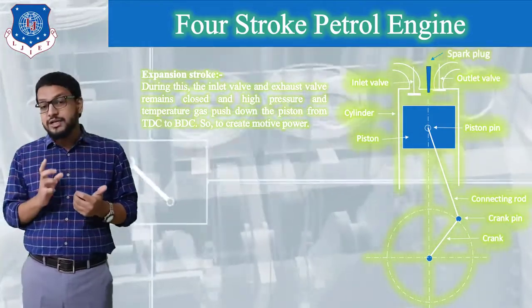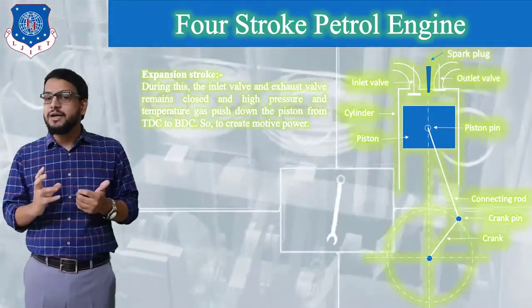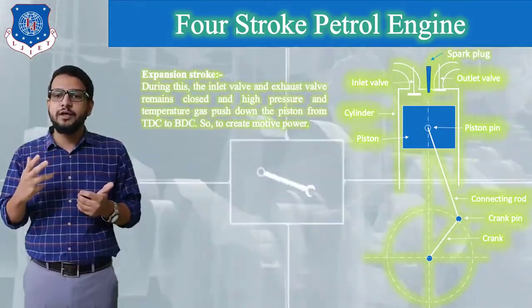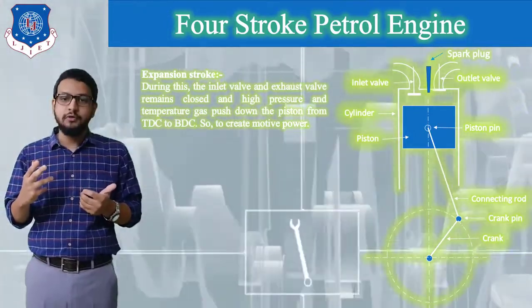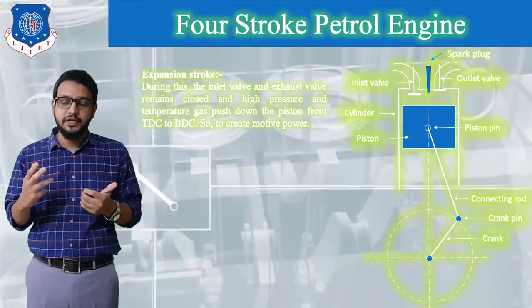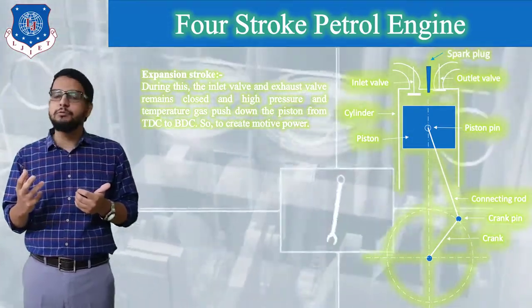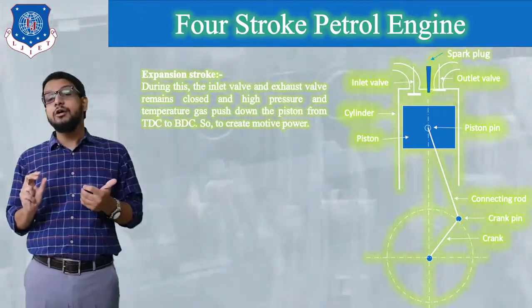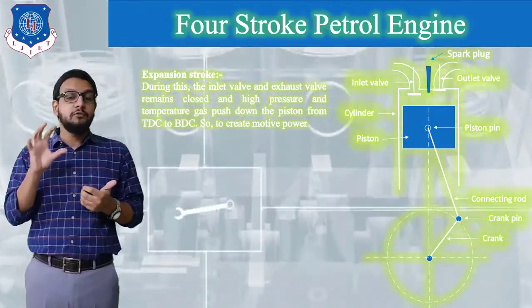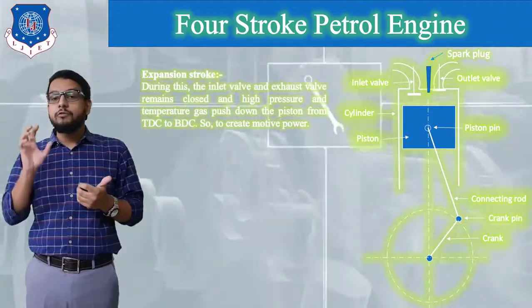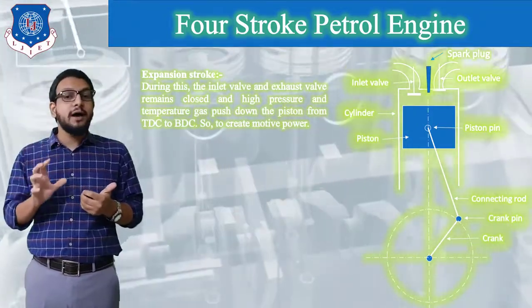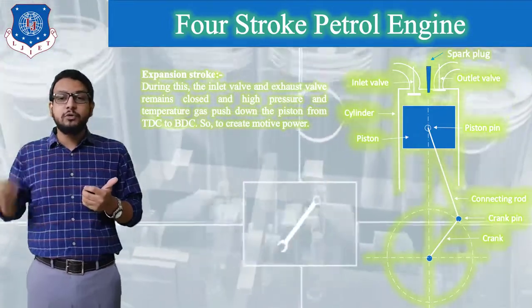Okay. So this speed is so high that if it is directly supplied to our wheels, then suddenly the speed of the vehicle can be increased. Fluctuation of speed can take place. So for this purpose, we are going to provide a flywheel on the crankshaft, which operates on the concept of inertia, which means during a power stroke, whatever additional mechanical power is generated is stored by the flywheel by means of its rotational motion.